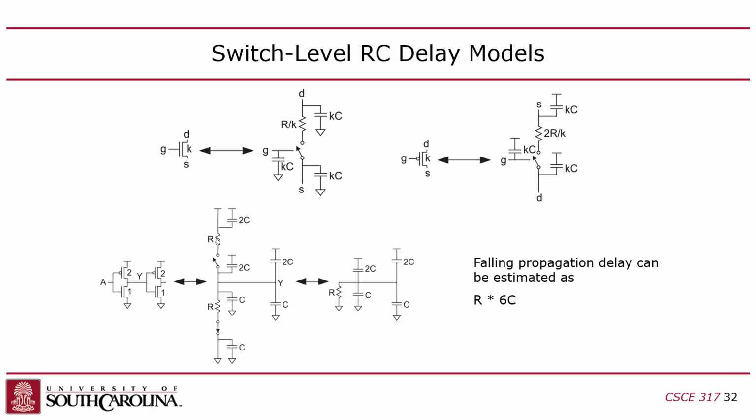So in terms of carrying charge, holes move at half the speed. Holes move at half the speed as electrons inside of a silicon lattice. Why is that? I have no idea. Some kind of chemistry, quantum mechanics thing. Holes have half the mobility of electrons. In order to make up for that, PMOSs are going to be twice as wide as NMOSs in your gates. Make sense? Okay, so that's why you've got a 2 here and a 2 here.